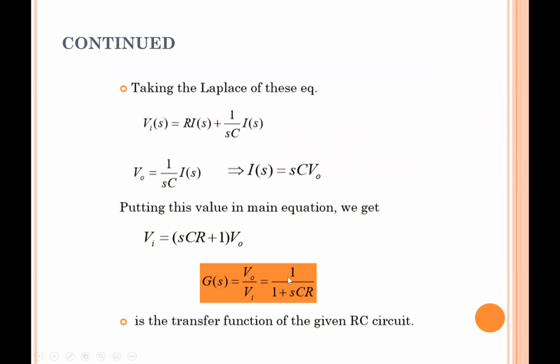And if we convert this system into a transfer function, that is, apply the Laplace transform and find its transfer function, then the power of s in the denominator will give you the order of the system. Remember the power of s: the highest power of s in the denominator of the transfer function gives you the order of this particular system. When we solved this, in its denominator expression s to the power 1 came, so this RC circuit is actually called a first order system.